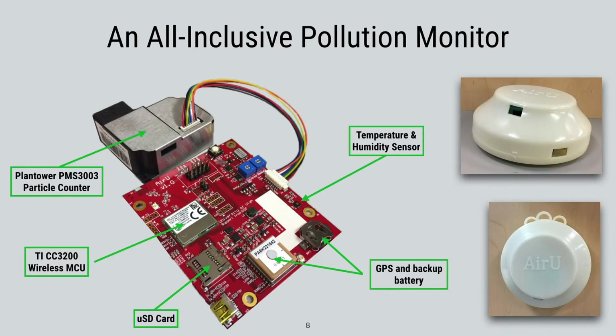And then I should also mention that a great step forward we've taken with these sensors is to calibrate every single PM sensor individually in our laboratory. And then that calibration data is stored on our server. So raw data points from the PM sensors go online to the server. At that point, the calibration is applied to them, and users can see the raw data as well as the calibrated data. And so you can see the trade-off and how well the calibrated data is actually adding to the raw data.